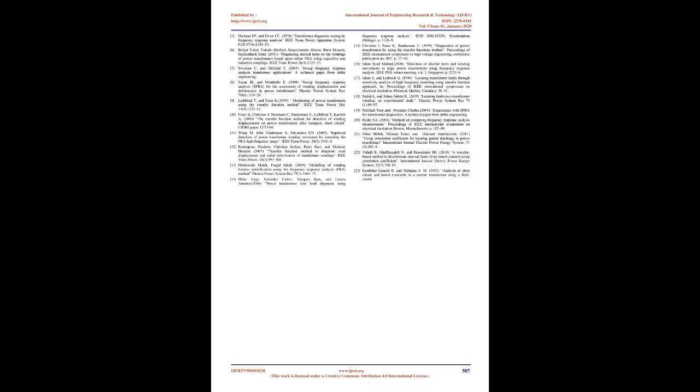It has to be highlighted that the reliability of the fault diagnosis is achieved by means of the qualitative approach based on the detection of the characteristic patterns that appear in the frequency response of the windings during the fault occurrence. Once the fault is identified, the computation of the statistical coefficients allows the quantification of the degree of fault. The performed experiments in this study proved that the structure and shape of the transfer function appears to be a function of the type, overall physical size and complexity of the transformer winding.